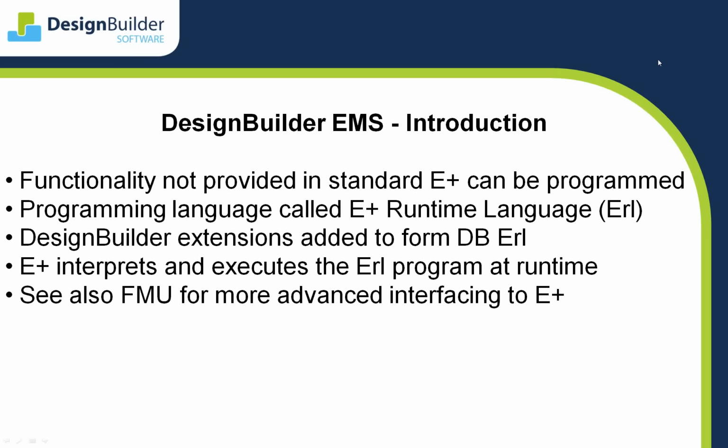The FMU enables you to link EnergyPlus to other simulation programs such as MATLAB, or to write your own code to enable functionality beyond that provided by EnergyPlus. The EMS, on the other hand, provides an easier way to write relatively simple code to customize the simulation. The EMS can access sensor output data and use this to control pumps, fans, HVAC equipment and set points, lighting, on-site electricity generation equipment, etc.